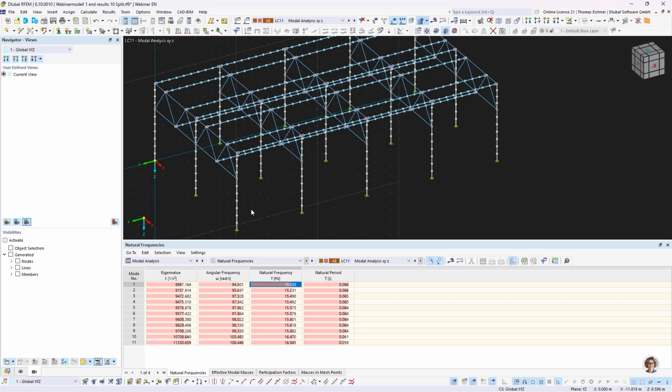That's how I call them. For example, this finite element point, with our mass matrix definition, could move in the x direction by 1. That would be one mode. It could be moved in the y direction by 1. That's another mode. And it could rotate around the z-axis. That's the third mode. So for each of these points, we have theoretically 3 possible modes.